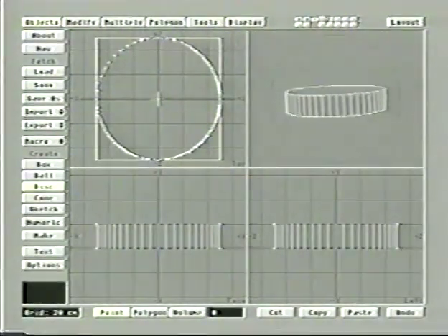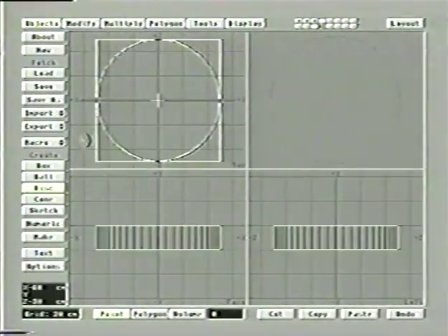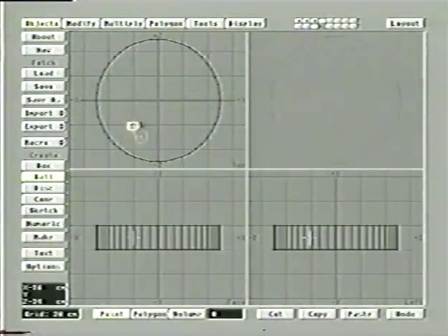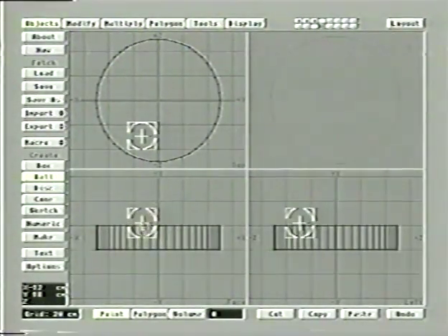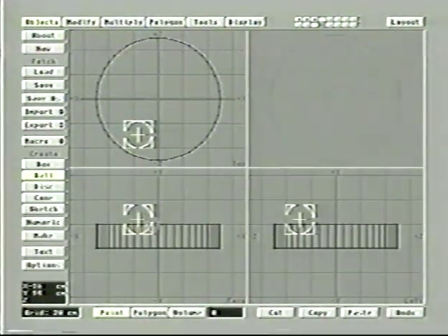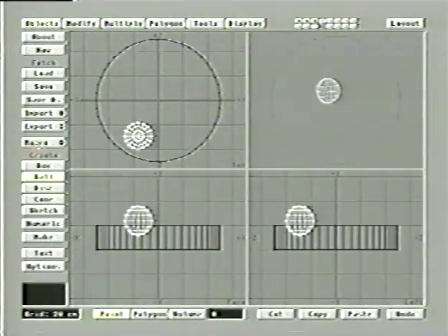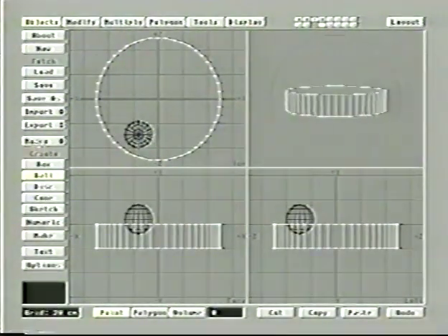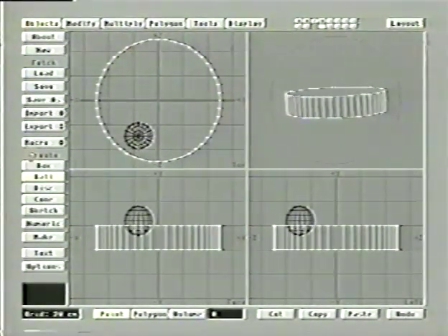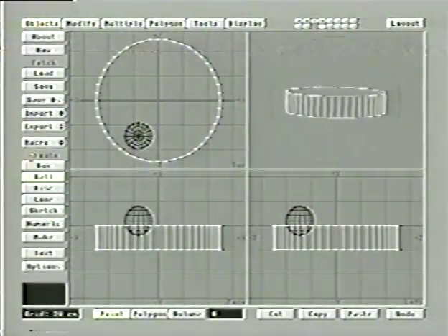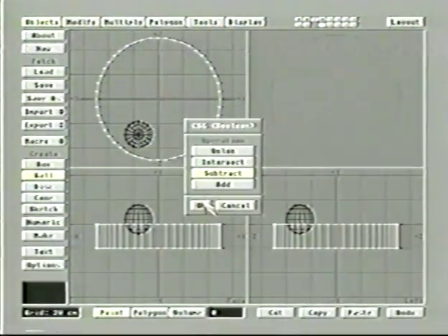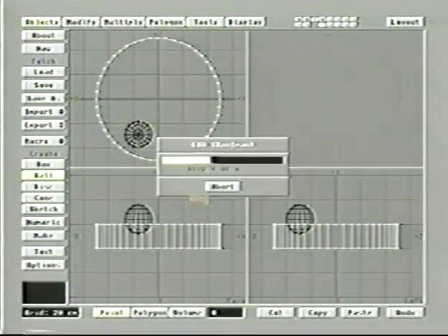Here's the wheel itself. Go to another layer, make the wheel visible in the background. And now I'm going to drag a sphere that goes part way in, but not all the way in. I just want to be able to take a chunk out of it. And since the sphere only goes part way into the disk, we switch our layers, that quote key again. You can see how the quote key itself can save 3 years of your life. So let's just do a Boolean, Shift B, subtract, and it's going to subtract the inactive layer from the active one, which will cut a chunk.